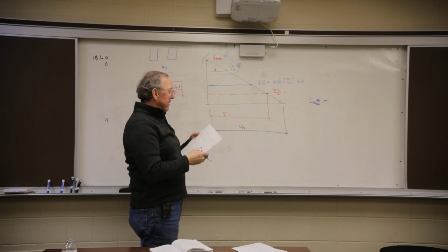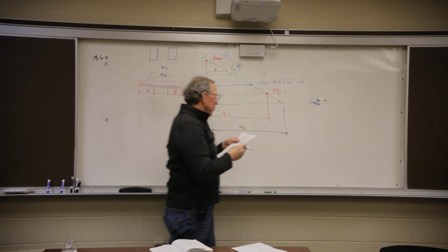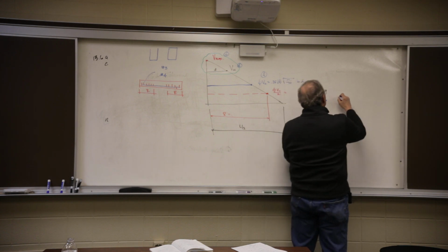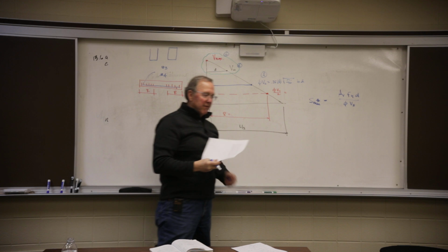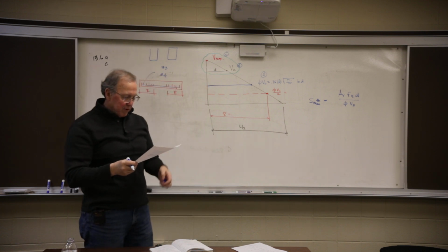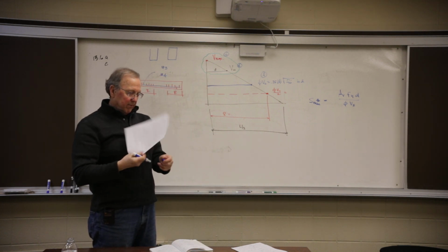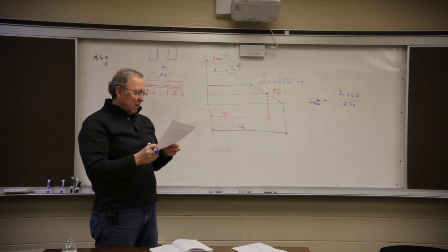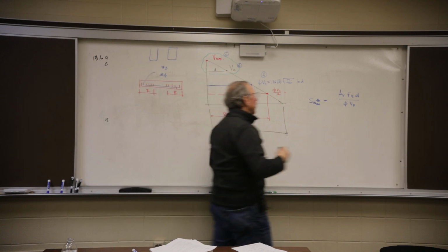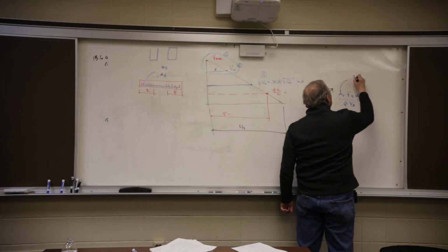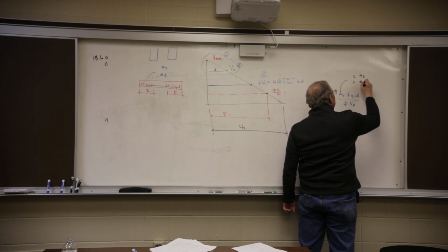And now I'm on letter N. N2 says S max is Av Fy d over phi Vs. Av is a number you calculated in letter L. So this Av is either going to be 2 number 3s or 2 number 4s.